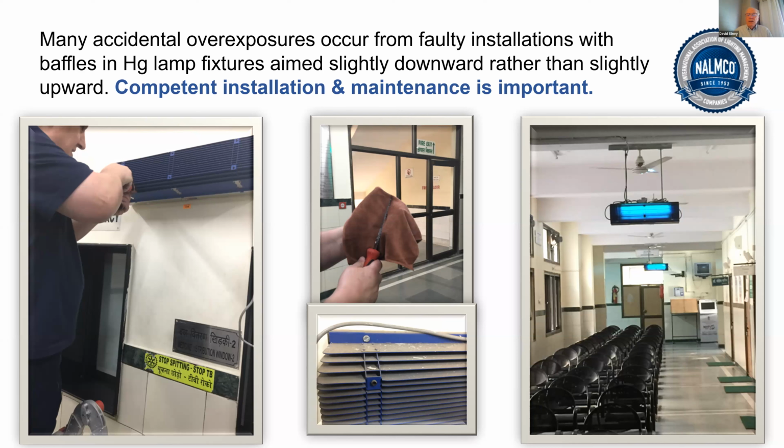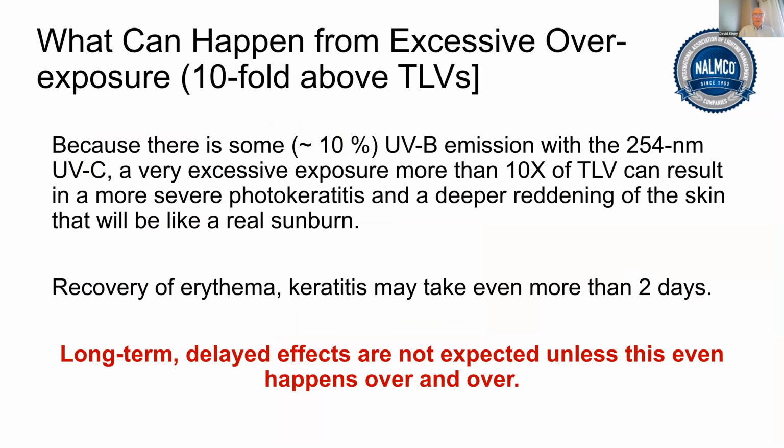So we see a final installation in this waiting room in a hospital or clinic where we have the UV fixtures suspended from the ceiling. And I want you to see that they're ceiling fans. So the ceiling fans are circulating air in the vertical direction to constantly mix the air where the virus or bacteria have been inactivated, and mix the clean air with any contaminated air, to reduce the concentration in the breathing zone of the people in that room.